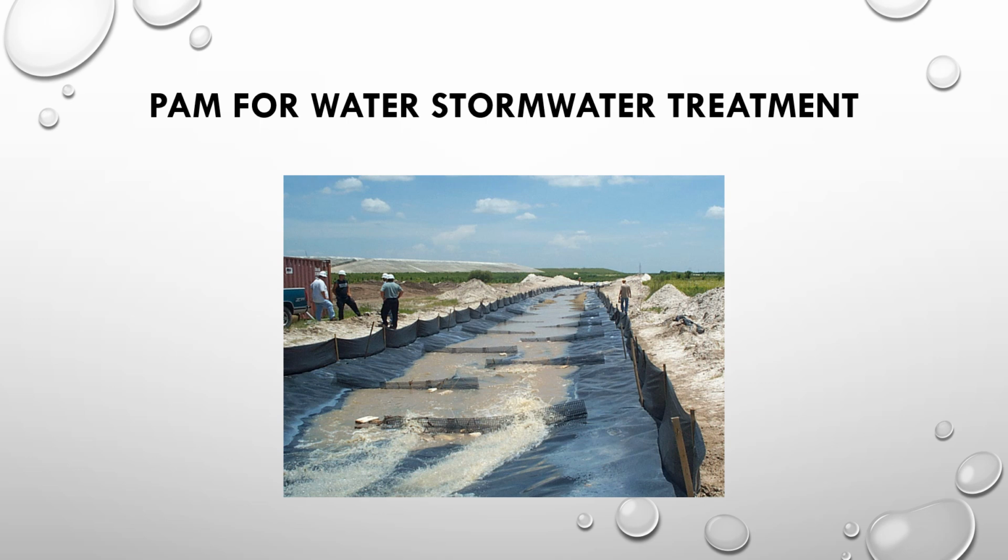So this channel is lined. It's got multiple logs there to be up to the correct dosage. They've added some of those black baffles to add mixing and reaction. And then again, we also want to collect the particles. And at the end of this channel, it's kind of hard to see, but there are some jute baffles.